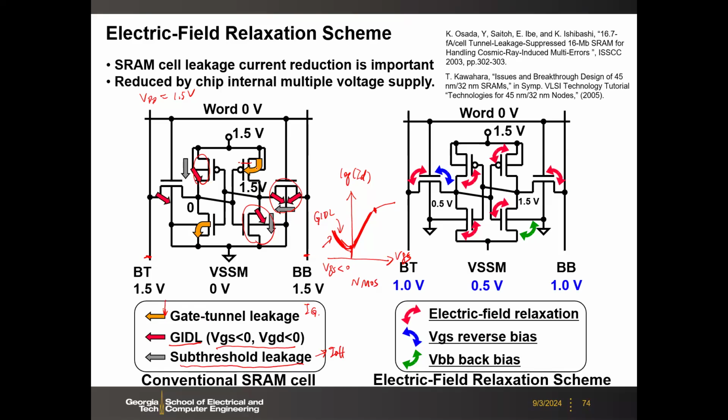Previously, when you had the poly gate and you shrank the SiO2 thickness below like 2 nanometers, you had direct tunneling from the gate to the channel. Then this becomes important. But today, I will talk about high-K metal gate in the following slides. If you use high-K metal gate, the gate leakage current is negligible today. So this one is not very important for today's transistor, okay?